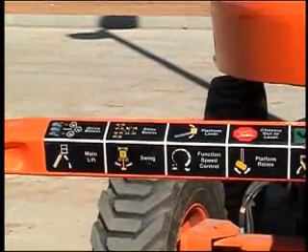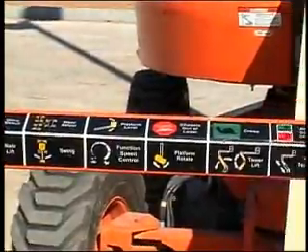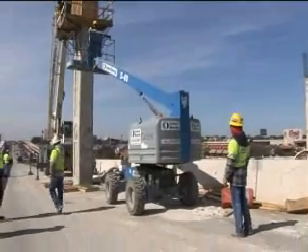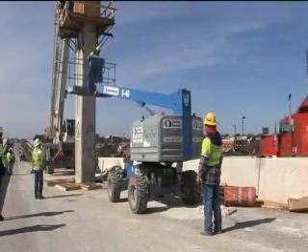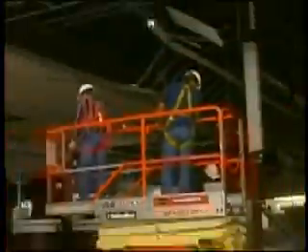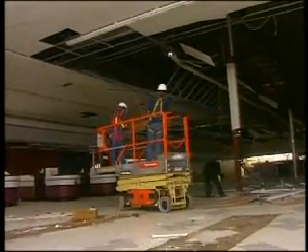Most lifts are equipped with various safety features. Never remove, bypass, or use these safety features for any reason other than specified by the manufacturer. Never modify a lift without written permission from the manufacturer or other qualified entity. If modified, the lift must be at least as safe as before modification. Employers should also be aware of local and state regulations and ensure compliance with those laws. Only authorized and trained persons should operate an aerial lift. Never tie off to an adjacent pole, structure, or piece of equipment while working from a lift.